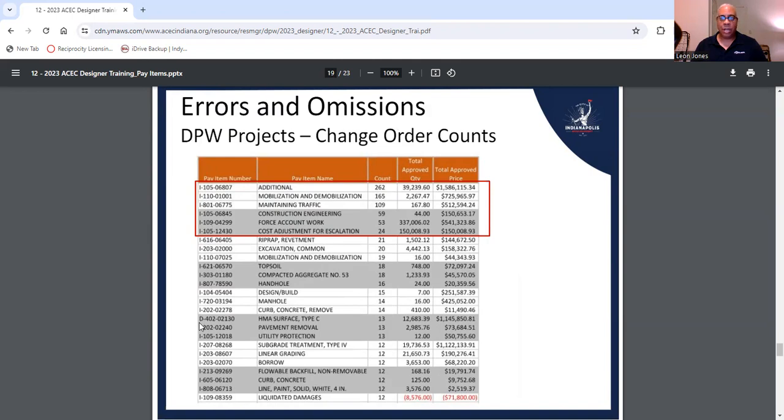Again, NDOT and most of the cities follow the same specifications. I think that's good because you have consistency. Now, there are some tweaks you can make, and I can tell you one that I'm writing myself with DPW, and it's with testing, where NDOT tests their asphalt with plate samples. I'm gonna go away from that and just use a couple of cylinders.